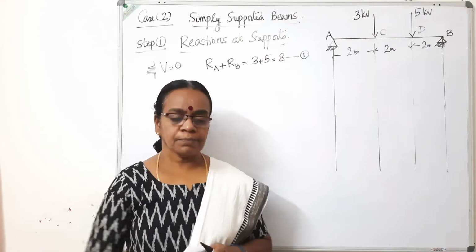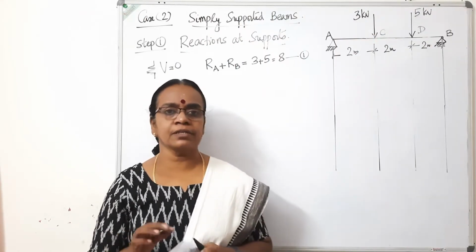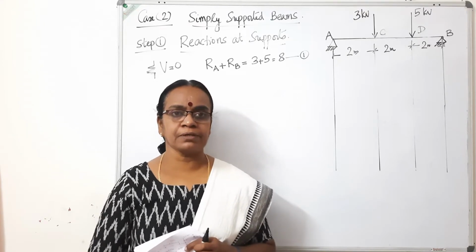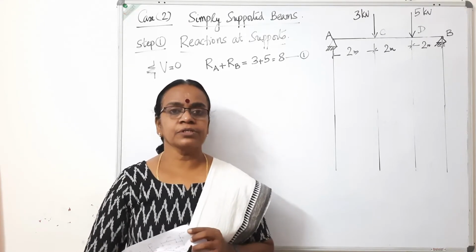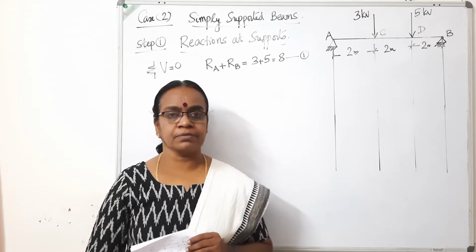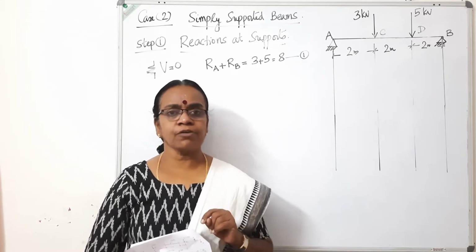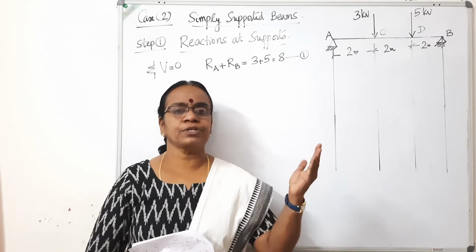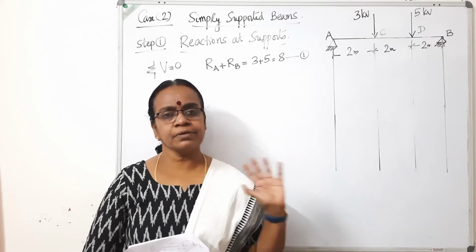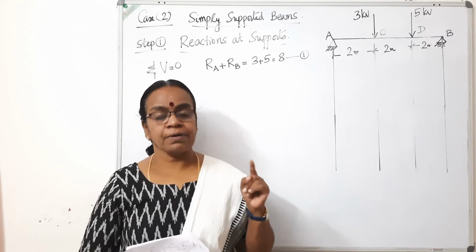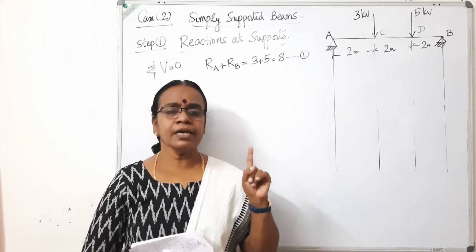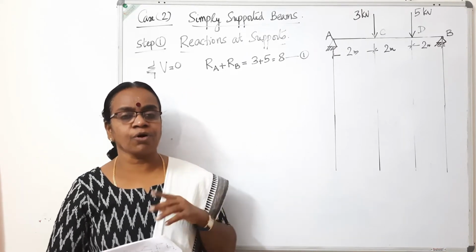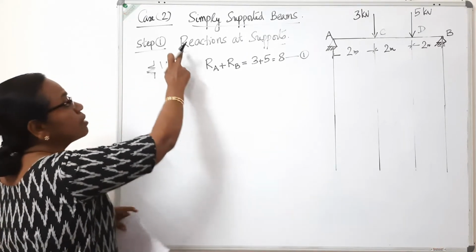Good morning. In the previous video, we have seen the analysis of cantilever beams, how to draw the shear force diagram and bend moment diagram. Now we are going to deal with simply supported beams. In the analysis of cantilever beams, we have only two steps: directly computation of shear force, and the second step, computation of bending moment. But remember, in the case of simply supported beams, the first step is always calculate the support reactions.